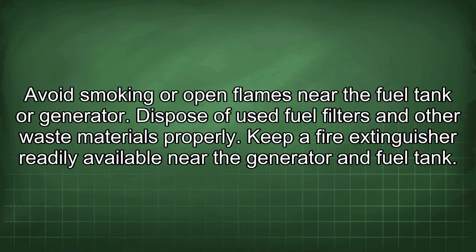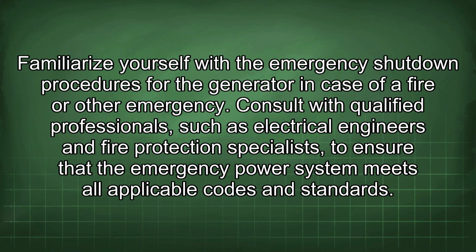Dispose of used fuel filters and other waste materials properly. Keep a fire extinguisher readily available near the generator and fuel tank. Familiarize yourself with the emergency shutdown procedures for the generator in case of a fire or other emergency. Consult with qualified professionals such as electrical engineers and fire protection specialists to ensure that the emergency power system meets all applicable codes and standards.